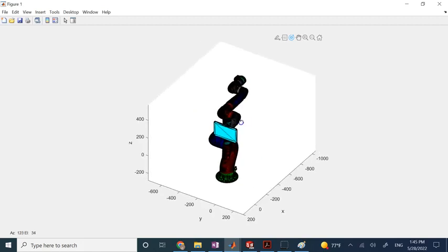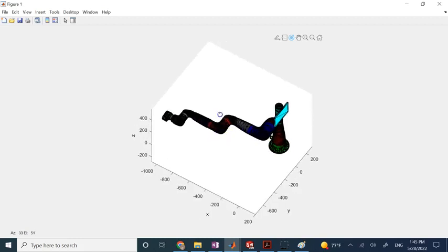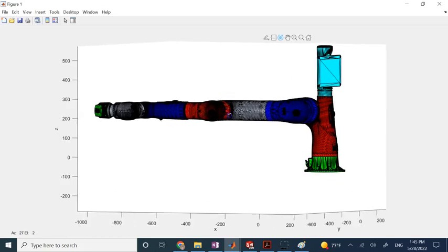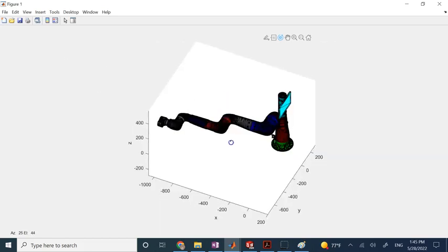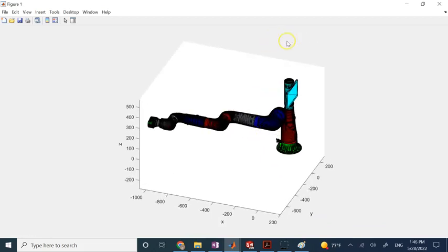Now the STL files are coarse. They do not have a ton of points on them. If the STL files were really heavy, it is going to be even slower than this. And you can click on any point that you want and use the data cursor, and you can get the coordinates of it. Use this data tip or data cursor, click on any point, and you can find the X, Y, and Z values.